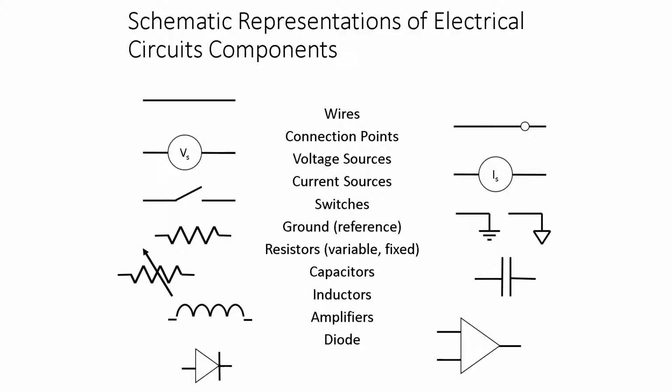A connection point, or we also call them test points, are points we design into our circuit board or into our circuit that we can test voltages or currents at to determine optimal function of that circuit and make sure it's working. Even in satellite CCAs and circuit cards, we always put test points so that it's much easier to diagnose if there's a problem or if something happens during vibe testing, thermal testing, or thermal shock or whatnot. This allows us easy, clean access instead of having to go in, or sometimes not even being able to test the circuit again.